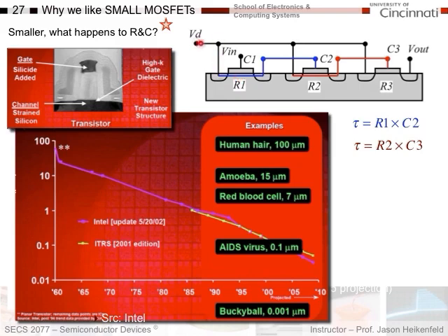So when I put a voltage in here, current goes through, higher current, lower R, feeds to the next capacitor, which has lower capacitance because the gate width was smaller, which then goes on to the next one, and basically the RC time constants add up. The whole circuit together gets much faster because the RC time constant for each one decreases: decreasing gate length, smaller C, smaller R. Both are advantages. If you look at a modern MOSFET, it looks like this.